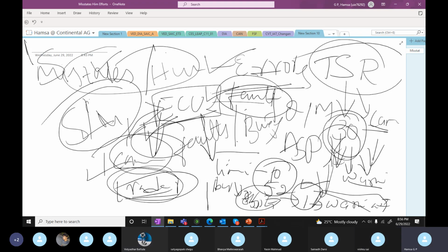Here, your ECU is identifying that the handbrake is not released. So if the handbrake is not released and you are trying to start the car, your engine will not allow you to start the car. Why? It has set the fault stating the handbrake is not released. When the warning indicator is high for that fault, only then will you get the indicator on your dashboard.